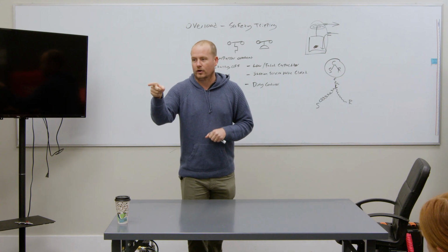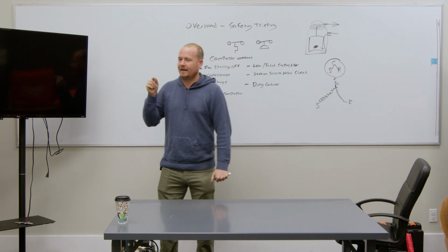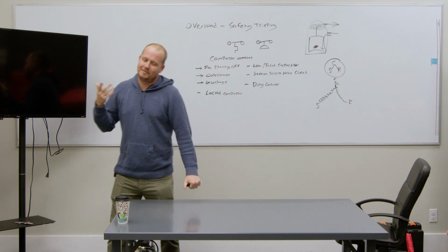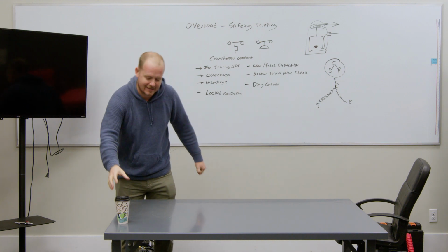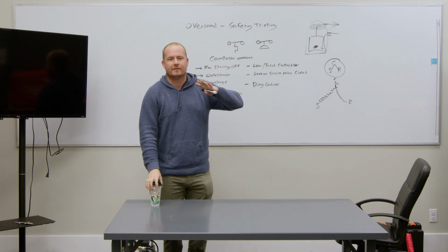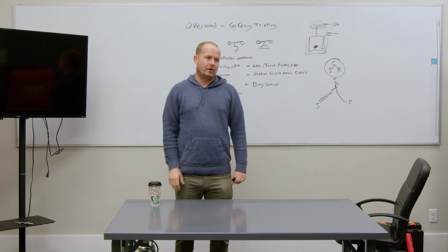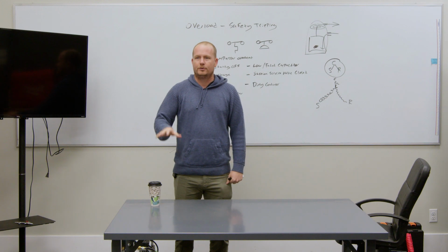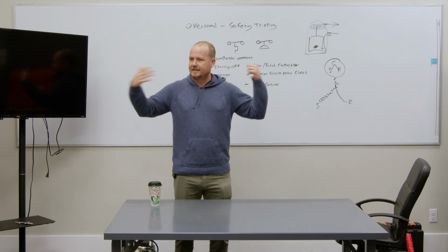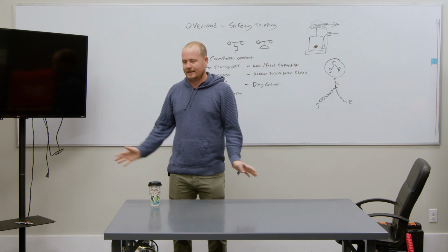Hot. Wrong. Cold. Meaning that if finally the thing didn't reset once, when you walk up to that compressor, it's going to be cold in the first place. The odds that you walked up to it, it was hot, you cool it, and this time it just didn't reset, it's not going to happen.